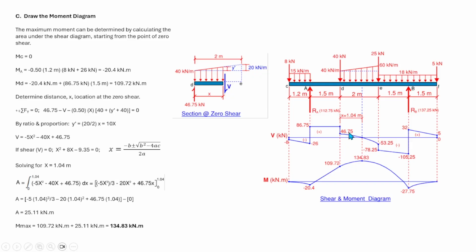So the second degree shear here in the moment diagram is third degree up to this point. That is third degree. From point A to B, that is linear. From this point to here, that is a second degree curve. Then in the cantilever end at point B to F, we have the first degree, which is linear. So in the moment diagram, it is a positive slope because this is positive shear. And that is a second degree curve until it reaches the point where the moment is 0. So we are done with the shear and moment diagram.